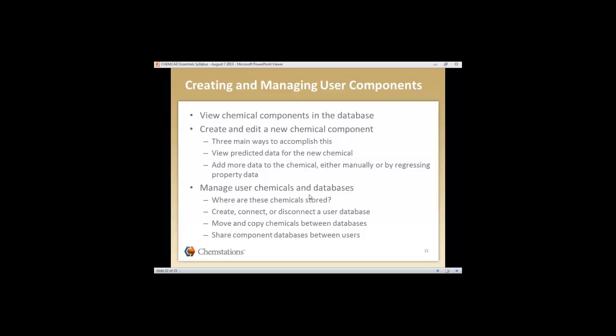The Electrolytes method is for very special situations. If you are trying to add a new ion for an electrolyte reaction, you might use the new component method electrolytes. And I would really ask that you call to talk with us, because adding a new electrolyte reaction is a fairly advanced topic.